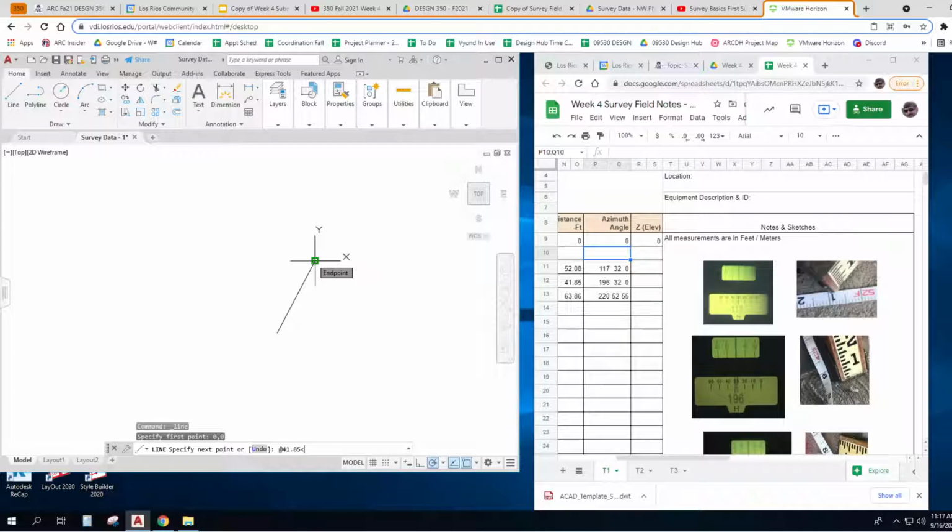The angle is above the comma, right next to the M. At an angle, 196 D for degrees, 32 minutes, and 0 seconds. You will almost never get 2 readings in a row with the same minutes and seconds, but it did happen that way this time. Enter. Enter again finishes that one.